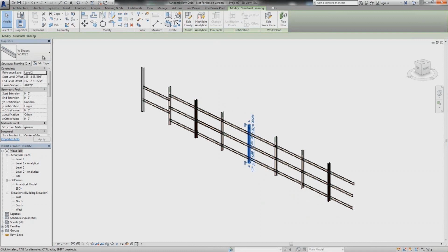Okay, so let's see what's next. What about AutoPlant specs? And I believe that's a little bit easier. Yeah, that's just using the spec editor tool. It will work with CADWorks or AutoPlant specs, or the older CADWorks specs. Referring to the Plant 3D spec editor tool? Yes. Right, and sometimes we can help assist with that too, but if you have access to the Plant 3D spec editor, you should be able to import your AutoPlant specs.